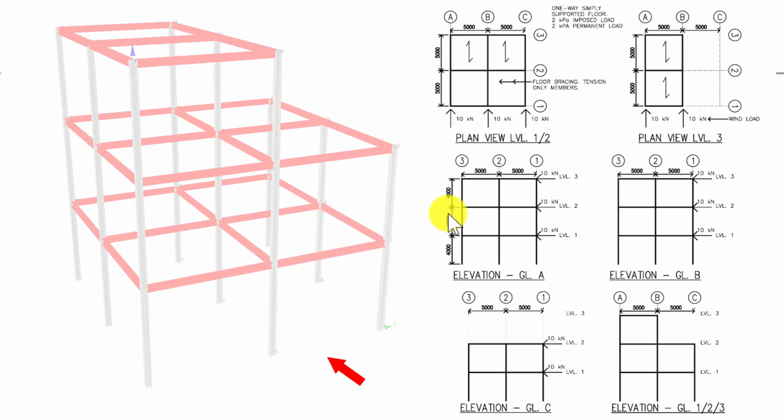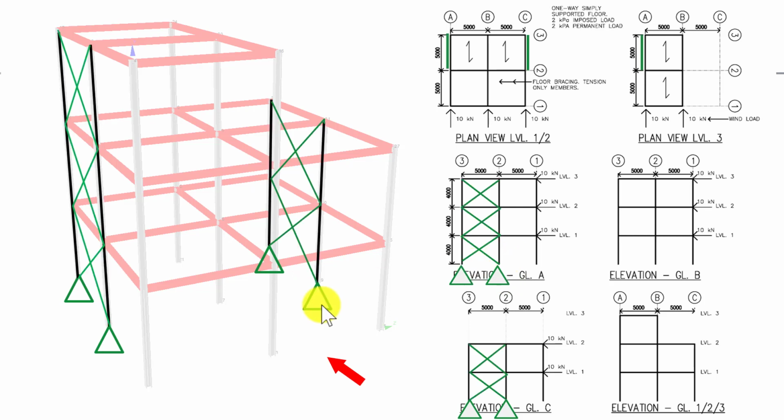So in this one I've decided, for instance, that I want to put the load to these foundations. I could have used other support, but I've decided to put it there and there. Those are the foundations I'm going to get all my lateral loads to, and then above those, I can create a braced bay. So here's a vertical bracing there, and then shown also in plan. And that means now this bay and this bay are now stable. This bracing is now very stiff.